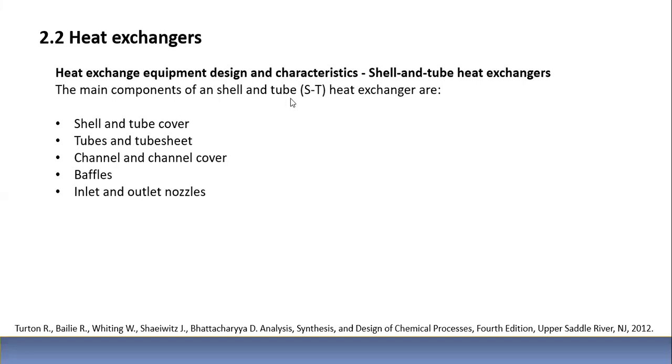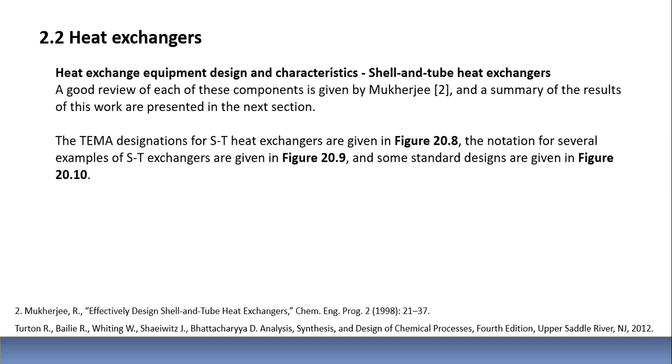The main components of a shell and tube heat exchanger are shell and shell cover, tubes and tube sheet, channel and channel cover, baffles, inlet and outlet nozzles. A good review of each of these components is given by Mukherjee, and a summary of the results of this work are presented in the next section. The TEMA designation,